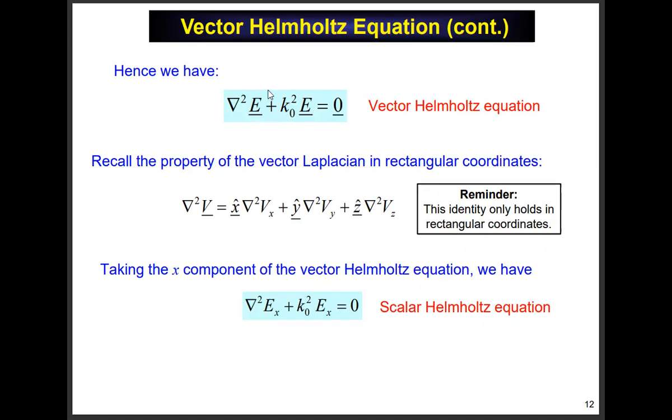But here is the vector Laplacian. So just pretend this says E everywhere, right? So the x component of the vector Laplacian is what? The regular, in other words, the scalar Laplacian of Ex. Now remember, if I have my vertical antenna sending out this spherical wave that's turning into a plane wave, I said it's going to have E vertical, x direction. So my assumption is this plane wave is carrying energy in the z direction, but it's polarized pointing in the x direction. That's why I took the x component. I'll pick back up here next week, but here is the starting point: this is the differential equation that Ex of the plane wave satisfies.